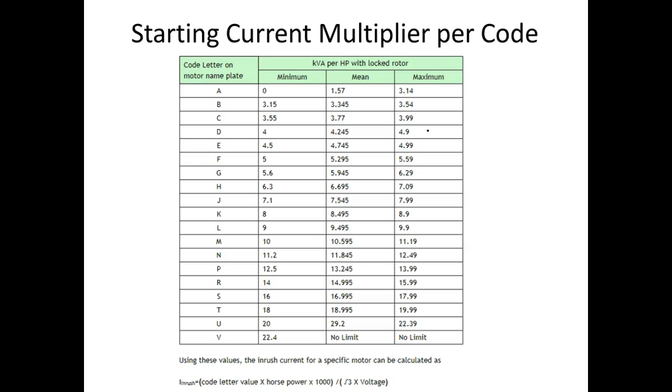And this is where your reduced voltage starter would come in. With a reduced voltage starter, you put resistors in series, or sometimes they use SCRs or triacs. They do it electronically, and we reduce the voltage to the motor, and then the motor doesn't create all that torque, and it won't pull all that starting current. So this is very, very popular in big motors.